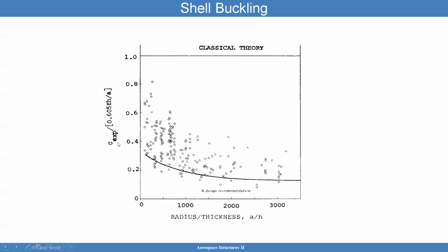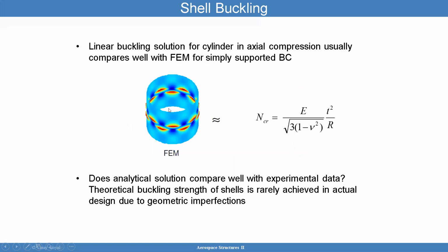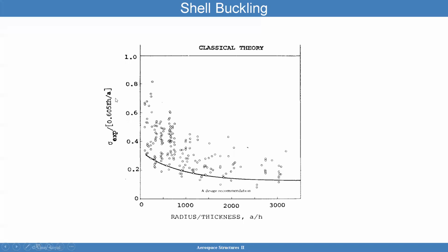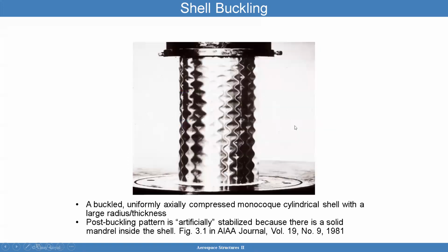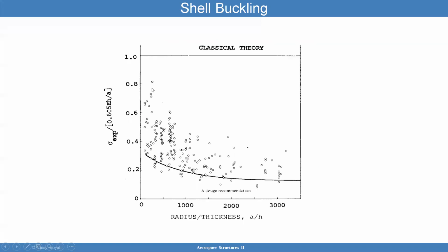So yeah, this is the ratio of the experimental buckling stress divided by the one predicted by analysis. And it's going to match finite elements if you ran it. I guarantee you that. This formula looks slightly different from this one here in the denominator. And again, I want to explain the reason one more time. I believe nu was assumed to be 0.3 or 0.33. So that turns this into a 0.605, that coefficient.